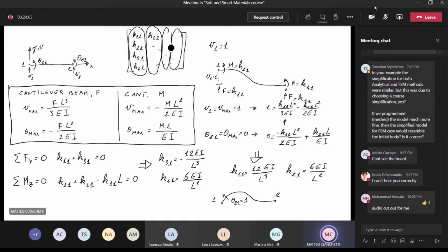Now we repeat for the last time: a column of K is the vector of loads at nodes to give the corresponding degree of freedom a unit value, while other degrees of freedom are 0. It is the fastest way to define this process, but the important thing is that you understood the mechanism to find and define column by column the stiffness matrix of an element.